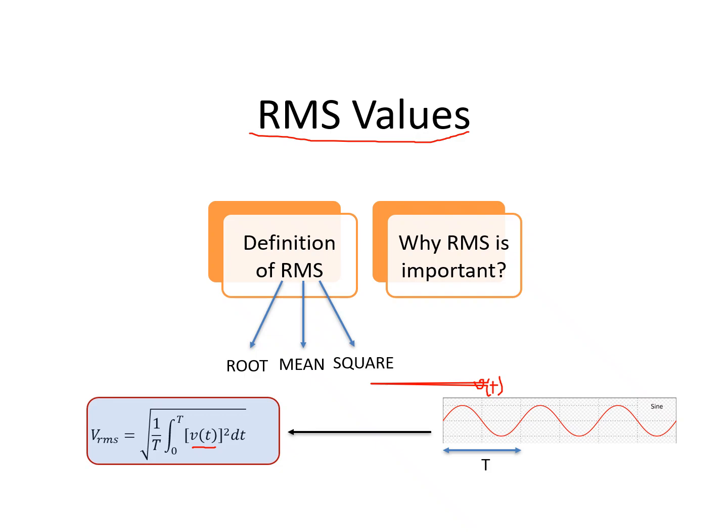I mean, if you calculate this in a real example, the RMS value would be the DC amount of this wave. And because it gives you an effective DC equivalent of this AC circuit, it is useful for power calculations.